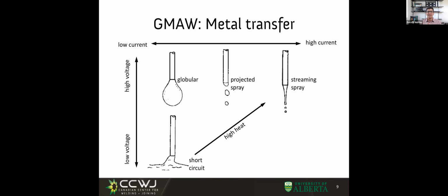So this video I just showed you talked about metal transfer. As we melt the electrode, we have, say, two extreme possibilities. Few big droplets, the wire melts as few big droplets, or the wire melts as many small droplets, right? When we have few big droplets, we call it globular transfer.